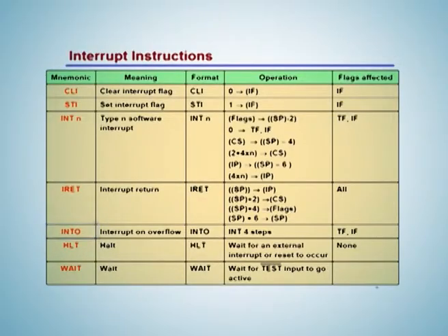The next instruction is INTO. As the name implies, INTO is an interrupt on overflow instruction. This instruction must be included after arithmetic instructions that can generate an overflow condition, such as addition, subtraction. It tests the overflow flag.